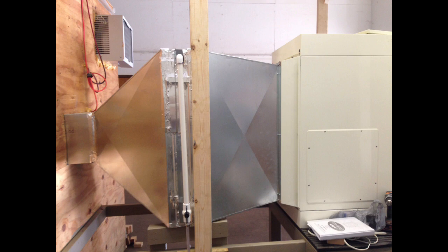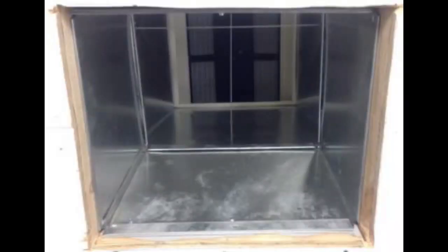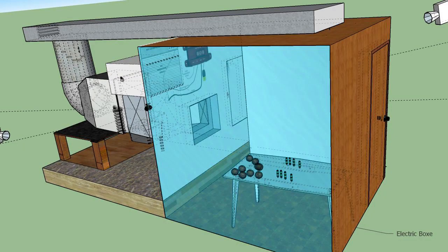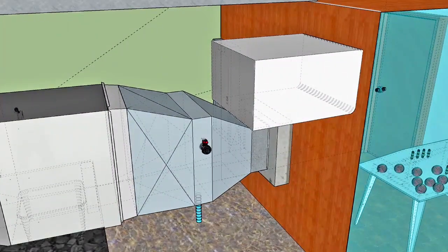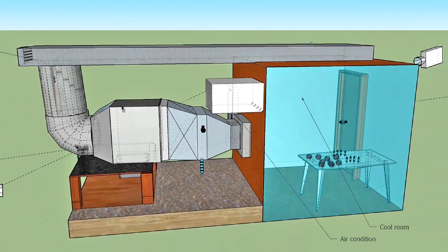The inlet into the cooler room was approximately 14 inches by 12.5 inches. The air was allowed to exhaust the cooler room with an opening in the ceiling of 24 inches by 14.5 inches. Ductwork was put in place to return that air to the input of the indirect cooling unit with the option for controlled volume of makeup air.